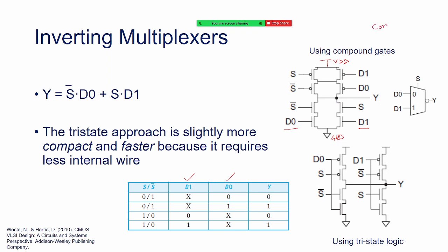So there are so many words I am using here. I can use control or I would say enable. Enable, and its complement. Usually I would say control when I'm using them to make transistors on and off, and I will use enable and its complement when I'm trying to make the whole circuit on and off. Control would be just for single transistors, NMOS, PMOS, or a pass gate. You can use any word, no matter, just say enable or control, because we'll see that these will be driven by the clocks. The clock goes on and off, and accordingly this network gets switched on and switched off.